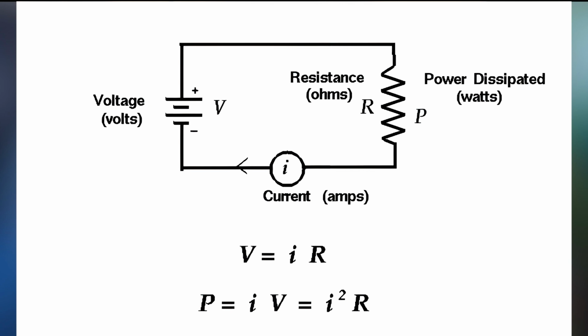In fact, what will happen is, assuming I have a large enough battery and whatever, I'll get so much current that the wire will start to glow and become very hot, and my battery will run down very, very quickly because I'm using up all that charge. The battery only has a certain amount of charge in it, as we all know. Sort of what that means is there's only a fixed number of electrons that are available to move around. Once you've moved out all those electrons, there aren't any more to come, and so you can't have any more current flowing. Now, the more rapidly I draw current from the battery, the more rapidly I'm pulling off those electrons, and so the more rapidly they're used up.